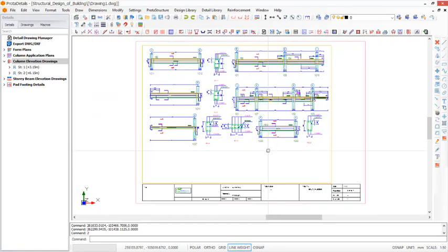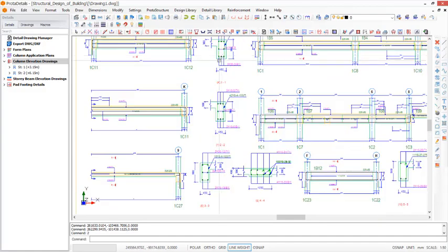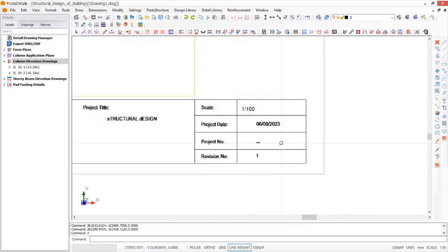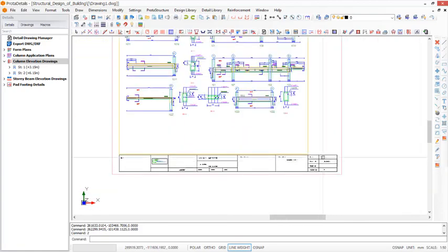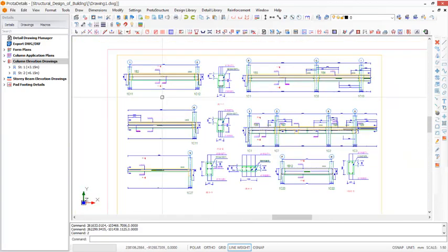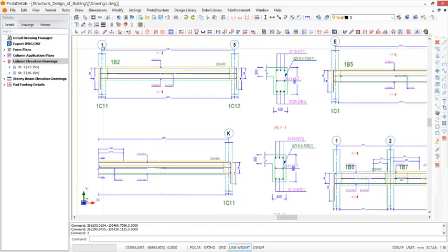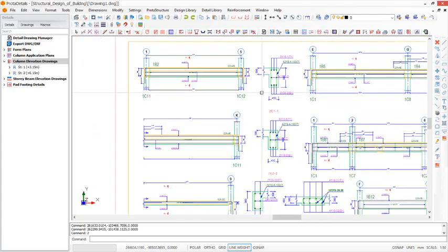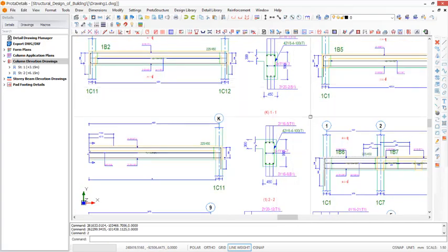Okay, and as well you can write the scale behind this, because this scale now are default. So when you're presenting drawings on the title block, let's say the title block might have a scale which is 1:100. The drawings in the title block should also have scales, which this particular one is a scale 1:50, and this is scale 1:25, which we have made the changes successfully. So you can as well write it under it.